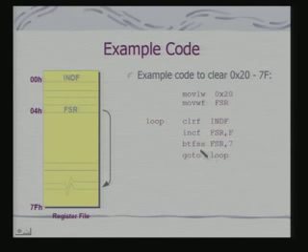As you go through the loop, what are you checking here? This will do a skip when it is set. So, this loop will not be executed when you have reached 7F. If you try to increment beyond 7F, you will skip, otherwise you will be clearing the content from 20 to 7F. This is an example of using indirect addressing.